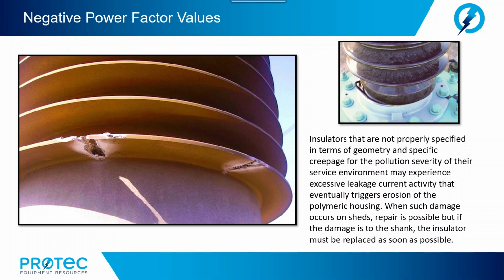All right. So make sure the surfaces of porcelain bushings are clean and dry to minimize the effects of surface leakage. Make sure all items such as wooden ladders or nylon ropes are removed from the equipment to be tested and are brought out of any electrostatic interference fields that could influence your measurements.